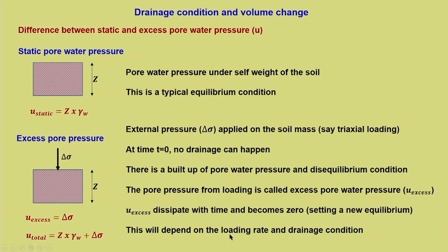Okay, so that is why it is written, it will depend upon the loading rate and drainage condition. Drainage condition, hydraulic conductivity of the soil on one hand, and on the other hand the loading rate, the manner in which the load is applied. Let us say it is an earthquake loading, the whole of the loading is going to be imposed in a very small amount of time. So, the buildup of pore water pressure will be quite high.